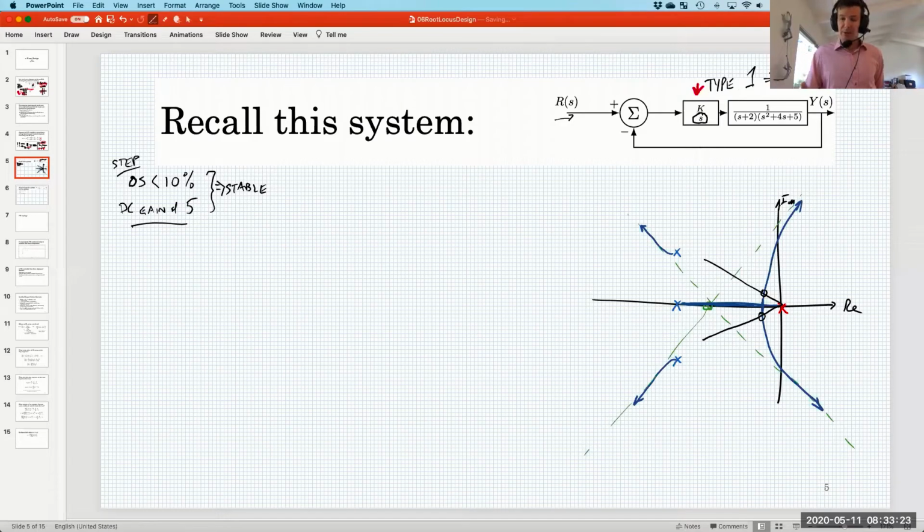So is this the right controller for our requirements? No, we didn't have to put an integrator in this controller. In fact, this integrator is actually what's giving us the headache here. So get rid of it. What if we just did proportional control? Would that work? These are the kinds of questions that I'd like you to start asking, especially about the term project, but in general as control engineers. If this controller doesn't work, what are my other options?